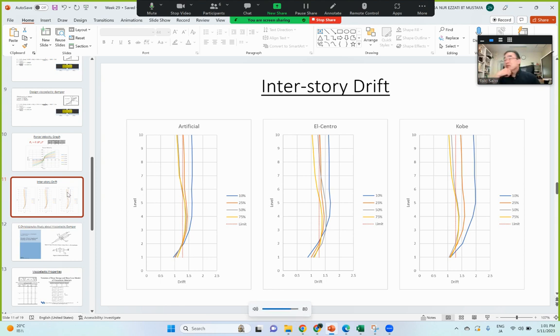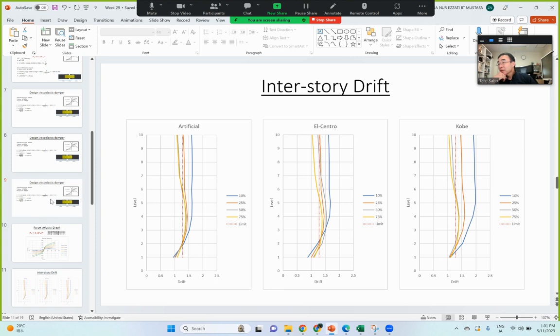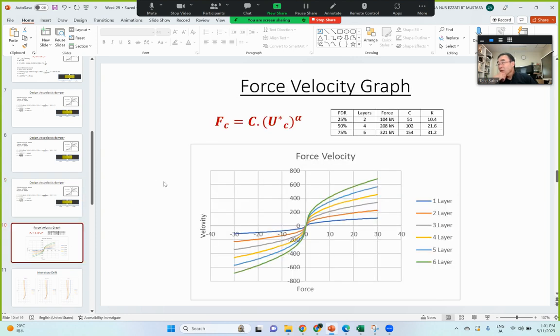Do you remember how much damping force, in the case of 400, Sensei, for each beam, with the hysteresis damper we used before? 400 maximum. Could you go back one slide? This one? No, the next one. So 400. So the viscous damper damping force exceeds 400 in case of high velocity, right? Yes. And in case of 30, maybe centimeter per second is the unit. Yes. So in this case, 600.